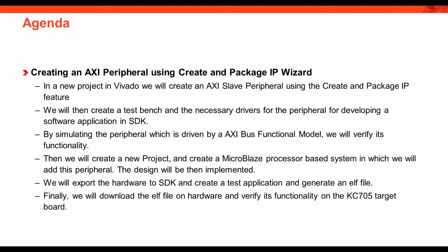Then we'll create a MicroBlaze processor-based system in which we will add this custom IP. The design will be then implemented and bitstream generated. We'll then export the hardware to SDK and create a test application and generate an ELF file. Finally, we will launch our application on the target board KC705 and verify its functionality.